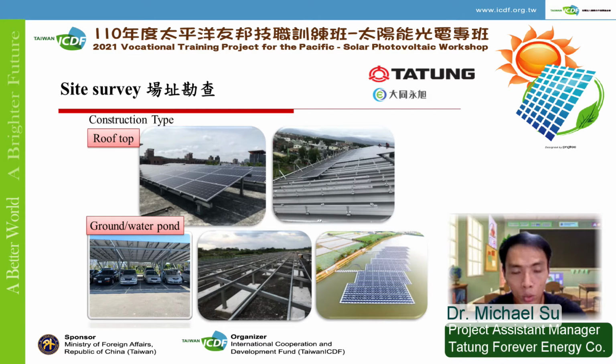For the typical sites that are on the ground, it's a bit simpler, but we would need to know the geology of that site. Was it a landfill before? If it is, then that means I can't secure my structure's foundation by drilling it down. I would need to use these large blocks in the picture to secure the foundation. Now, for the ones that are over the water, we need to consider the hydrology. For example, the flooding situation over the past 20 or 50 years. If there are any ongoing flood control operations in the area, will there be a flood? These are the things that we need to evaluate when surveying the site.